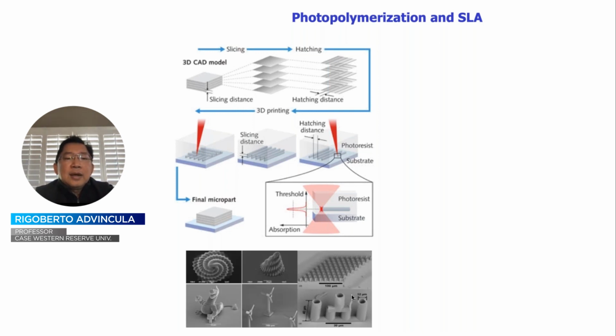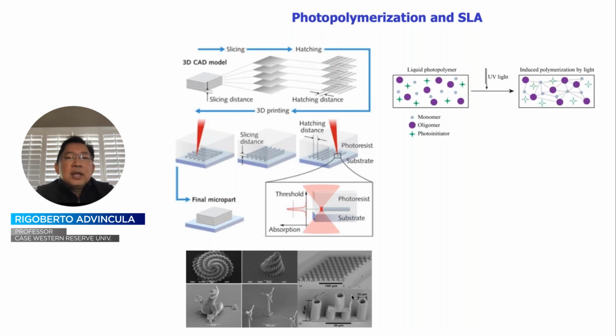Now, in particular, trying to do these things in high resolution will involve a type of nanolithography or even two-photon polymerization, which I'll explain to you in a little while. But basically, the same ingredients comprising of a resin that contains the monomer, the oligomer, and the photoinitiator can be activated by initiation. So in a traditional process where you have linear polymerization, the initiator leads to propagation step and then finally termination.